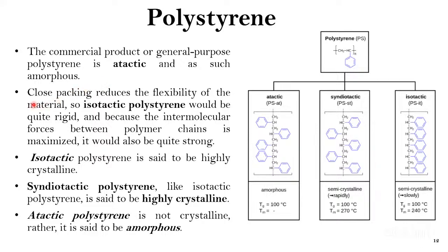Okay. So close packing means, if I talk about the syndiotactic and isotactic, due to this well-arranged structure of the benzene rings, they are very close packed. Okay, that is the reason they are very difficult in flexibility and they are quite rigid in nature, as they have very strong intermolecular forces, and that is the reason they are quite strong.